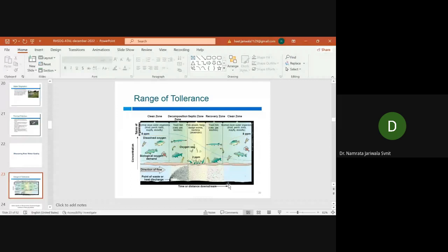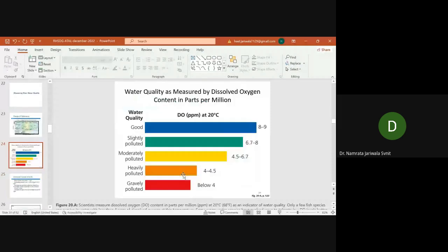If your wastewater has less organic matter, then the DO, whatever is available, will not be utilized. And for that, we have a limit of 30 milligram per liter as far as the Indian standards are concerned. So one parameter with the help of which you can measure healthy water bodies is DO, dissolved oxygen. Generally, you can see the DO with a color combination.